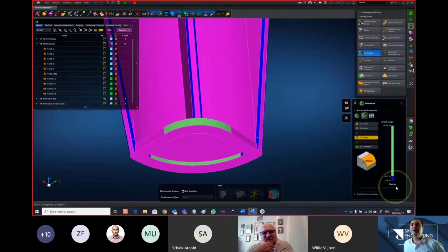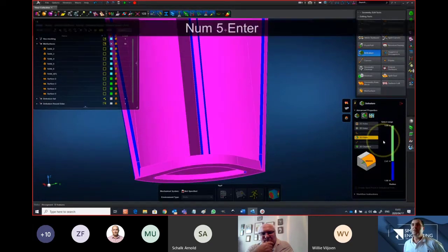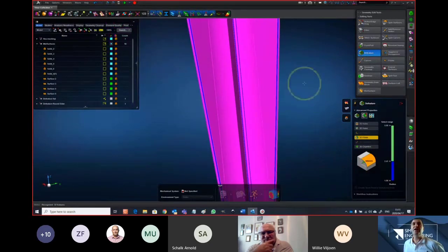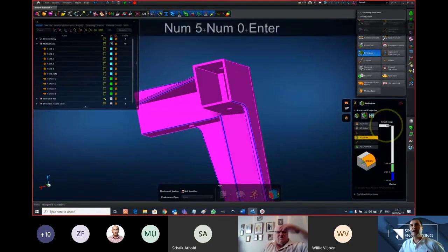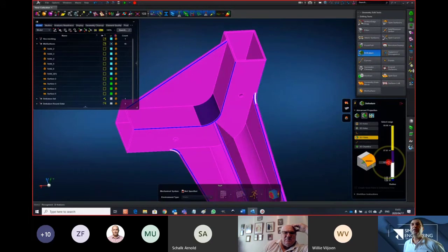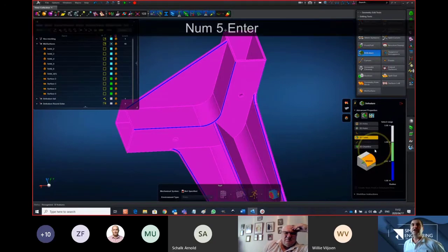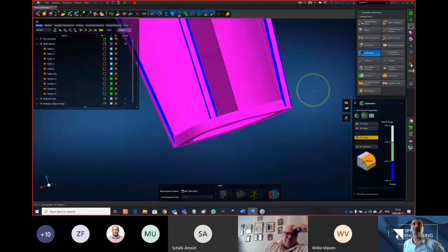Now, if this range becomes very small and difficult to see, you can also change the number over here to a smaller value so that the different ranges are clearer. And if you want to differentiate between the other sizes, well, let's just go back to the original. You can at any stage just click anywhere here and manually change those values as well, to create different groupings of the differently sized features.